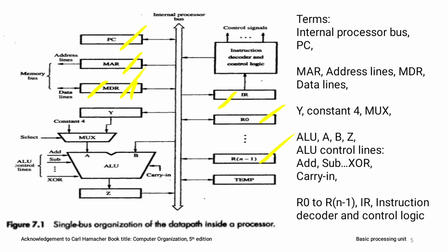Next, this is the instruction register. Whenever an instruction word is fetched from memory, it is saved in IR, the instruction register. From it, it is taken to the instruction decoder, which decodes and assesses what operation must be done and where the operands are. Accordingly, the control logic generates control signals and sends them to different parts of the processor to perform the needed activities.